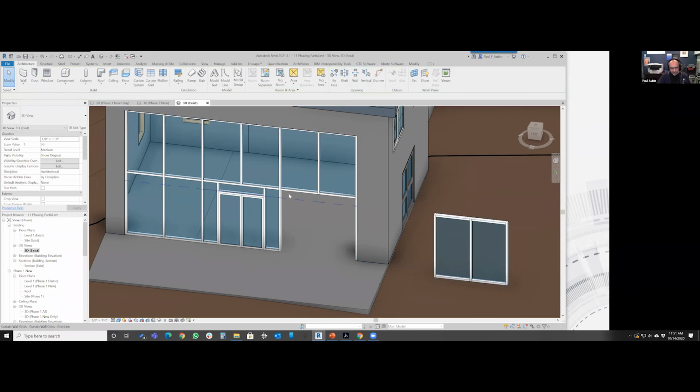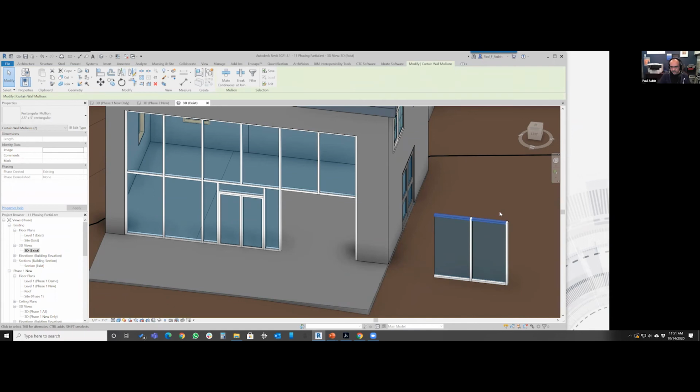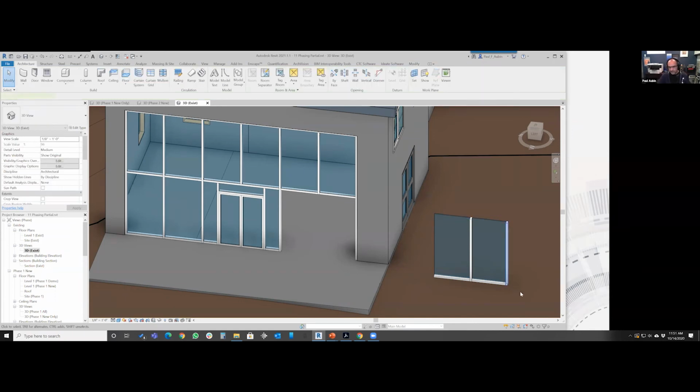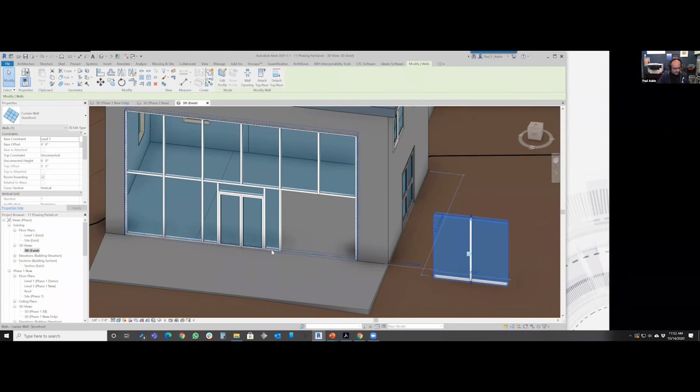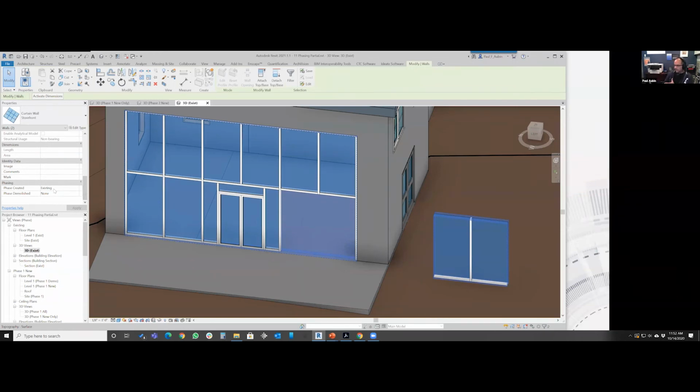And then we've already got a mullion here and around there, right? So the only mullions we need are the two at the bottoms and the ones down at the top. So, again, you unpin, select those, unpin, and this guy, and unpin. I'm just typing UP. So then this, right, you slide in right there. And it would be these elements that you would make existing. And notice that the curtain wall itself can be existing, okay? And all of its subcomponents then also become existing.